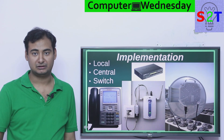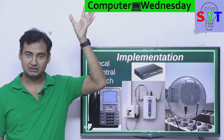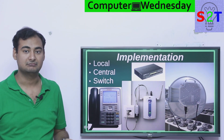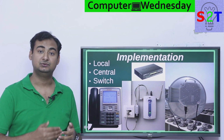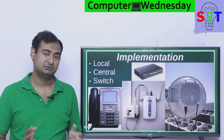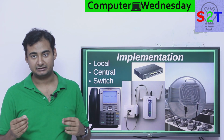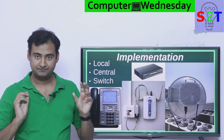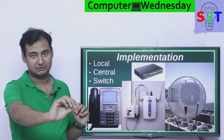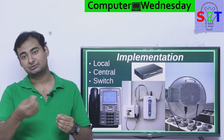You can have one-on-one. So let's say all you are dealing with is, hey, I have one Wi-Fi router that I have to put on top or on the second floor. Many of you have multi-floor homes. In that sort of scenario, you can do this. Now you might be like, okay, my router is not PoE enabled. You don't have to worry about it. There is a PoE injector you can buy, and from that PoE injector, it will be simple. You plug in your DC adapter and you plug in your data, then the cable becomes PoE enabled, and from the other end where you are receiving, you can do the same.